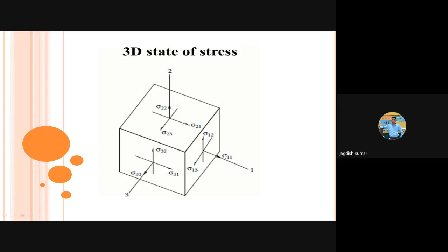And then we talk of, say, X dependence of sigma. We may say sigma 1 depends upon X. If it is not uniform, then the stress may be different. Stress here may be different on this face, and stress somewhere in the middle of this cube, acting along the X direction, may be different. That is where we define it in terms of X dependence of sigma.